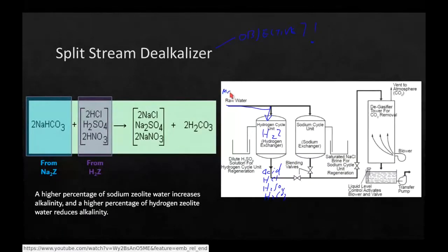We've got, say, magnesium chloride, permanent hardness. We've got calcium bicarbonate maybe coming in as temporary hardness. And maybe we've got magnesium sulfate coming in as permanent hardness. So this stuff is in the raw water, and it's going to turn into these acids.